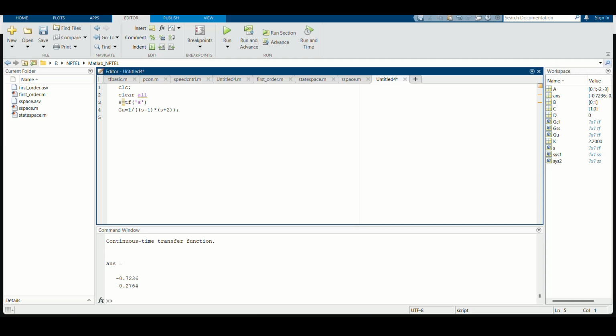You can calculate these by theoretical means using the Routh-Hurwitz criteria, or by analyzing the pole locations from the characteristic equation, which gives the expression for poles, from where you can get Kp and Ki.